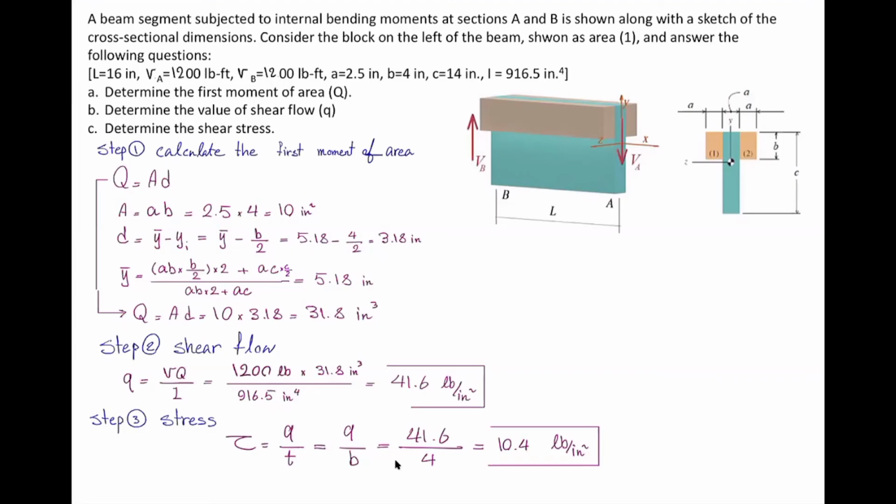Again, we wanted to review these problems to make sure that we understand two important things that are sometimes confusing: how to calculate Q, or the first moment of area, for the problems, and how to calculate the thickness that is needed for determining the shear stress in the problems.